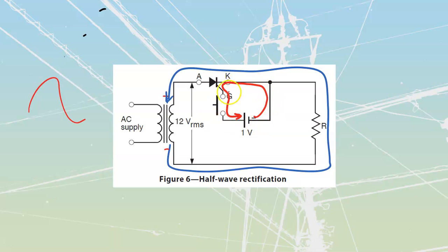This DC current, represented here by the red, has got zero interest in going anywhere inside of the AC circuit. Same as the AC circuit has got zero interest in going anywhere inside of this DC circuit. They both just share this one little line where they're going through, and all that's going to do is give us what we refer to as a DC offset to that AC value. Okay.